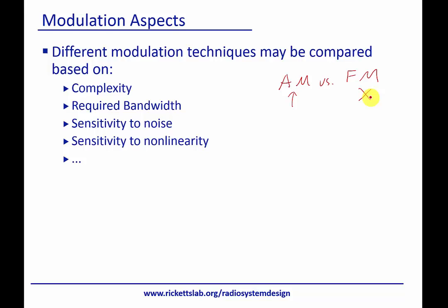But after a while, people learned, in particular, Shannon showed us that we can actually increase the signal-to-noise ratio by increasing the bandwidth that we use. And so the way to think about it is in frequency modulation, if we take a signal and use a very large frequency modulation, we can actually increase the signal-to-noise.